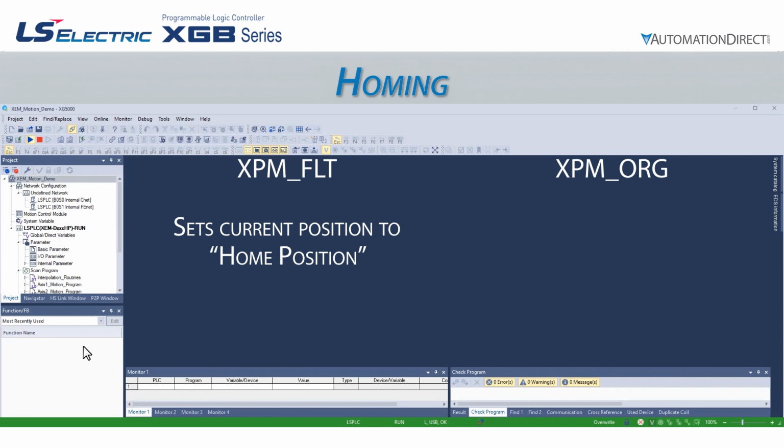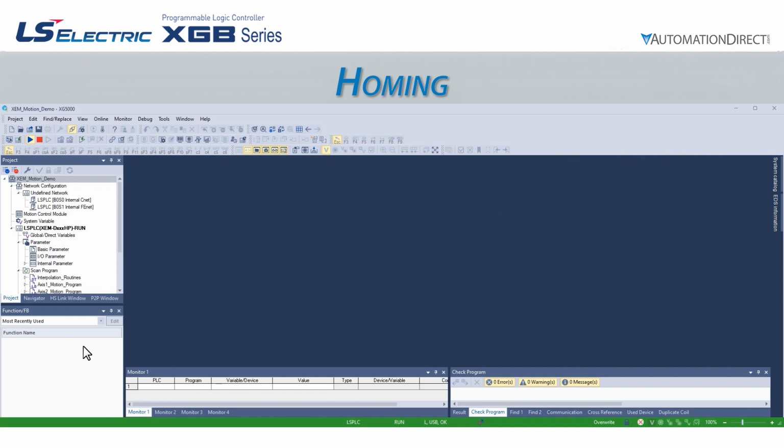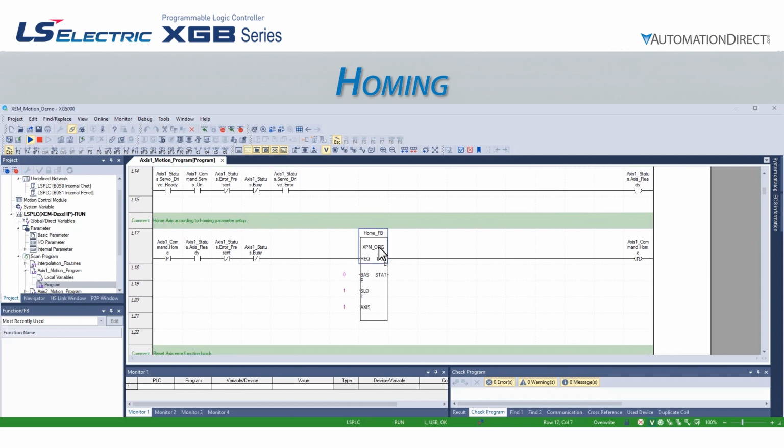The XPM ORG function block is used with the parameters we set in XGPM to initiate a move to a home or origin point. Our project uses an XPM ORG for each of the axes. Let's look at the function block for axis 1. We maximize axis 1 motion program and double-click on Program. We will scroll down and find our home function block resides on line 17 of the ladder code.